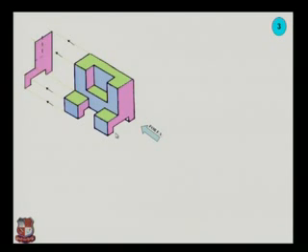As we see in the front view, this pink portion will come in the full line in the orthographic projection, and this hidden object from the front view is invisible. So this vertical line will be drawn as a dotted line, which is invisible.